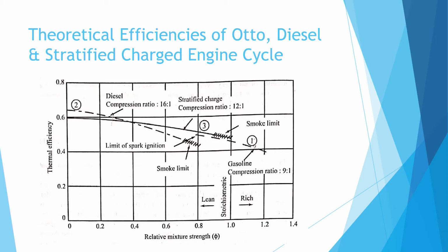Minimum specific fuel consumption is obtained at a relative fuel air ratio of 0.85 to 0.9, below which flame propagation becomes slow and cycle to cycle fluctuations occur. This limits the use of lean mixture and hence limits the gain in thermodynamic efficiency in SI engine.